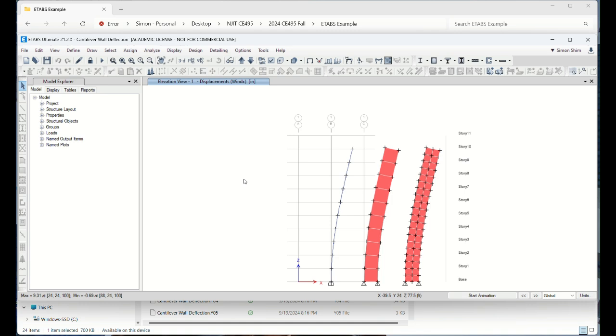Since this is also a relatively coarse mesh, and this wall is relatively huge, 10 by 10, can I use one element or can I mesh it more finely like this? This is one example to try and mesh it. I see deflection is a little bit more. Because now what is inside? They use these four nodes to define the internal stiffness. But obviously, since there are only four nodes, what about inside?